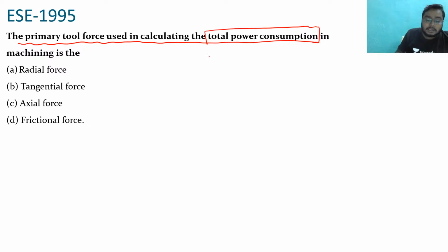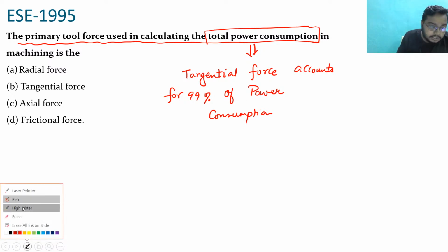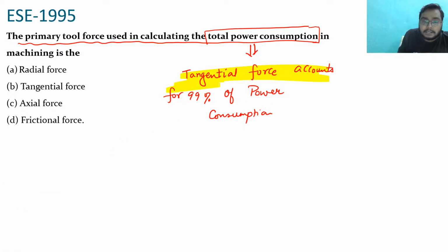The main point is this: tangential force accounts for 99% of power consumption, and the tangential force comes as cutting force.